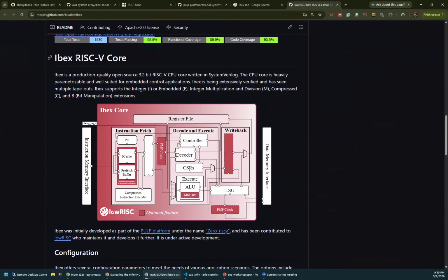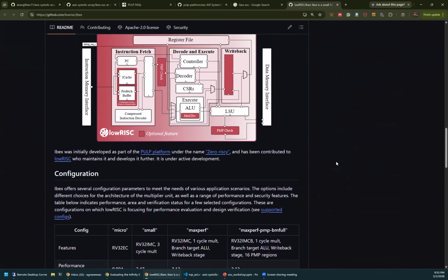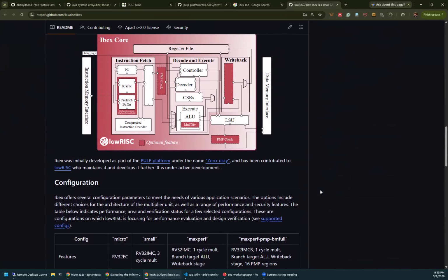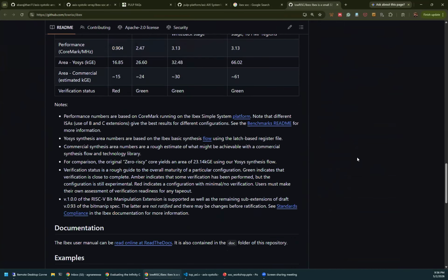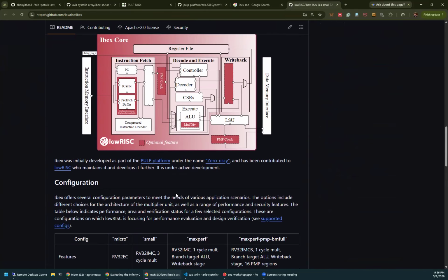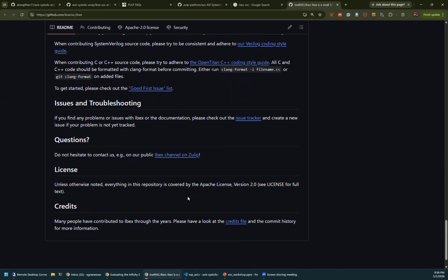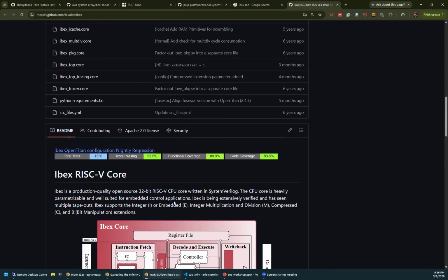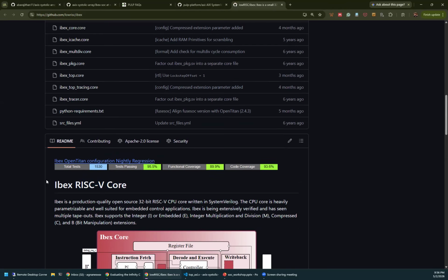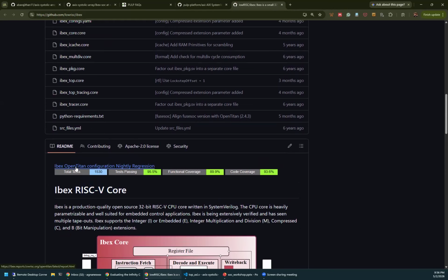The idea is it is a RISC-V core, so you can build an SoC out of this. You can put multiple things together, like memory, your accelerators, and connect them together into an SoC. It is used in some of the big projects, like OpenTitan. OpenTitan is a hardware root of trust, a hardware security project, pretty famous from Google. So they also use Ibex.